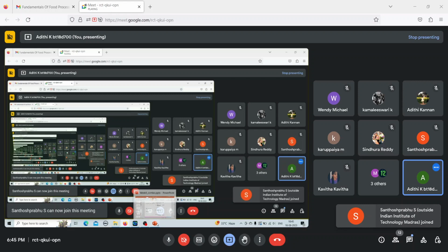Is this clear? So there are three different processes involved. First, heat has to transfer from the steam to the outer surface. That will have a certain resistance due to the outer film that is forming. So as steam touches the tube, it will start condensing on the surface of the tube. That will form an outer film-like layer that will cause some heat transfer resistance. Then there will be resistance due to conduction, that is the heat has to transfer from the outside of the tube to the inside of the tube.